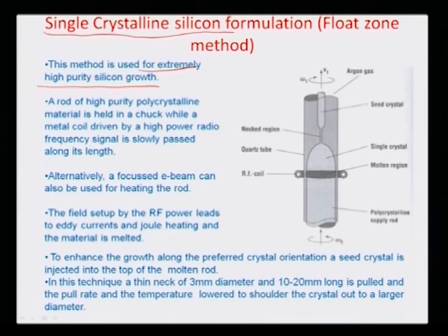You have the concept of a seed crystal in this method as well, as we had in Czochralski. However, in this particular case, as you can see, there is a polycrystalline rod which is being pushed into the small orifice here, and by means of non-contact heating, like an RF mechanism, you heat this particular surface of the wafer to almost its melting temperature, while pushing the polycrystalline rod all the way into the orifice.